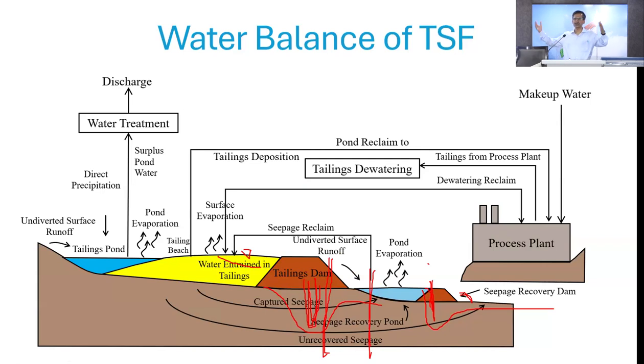Because when it is exposed to outside, I don't know what has happened inside. But how will I know? Only if there is seepage through this. Then I found that there is no correlation. Why I put 2 piezometers here is just to draw a phreatic line. Suppose I tentatively draw a phreatic line, how it passes through.